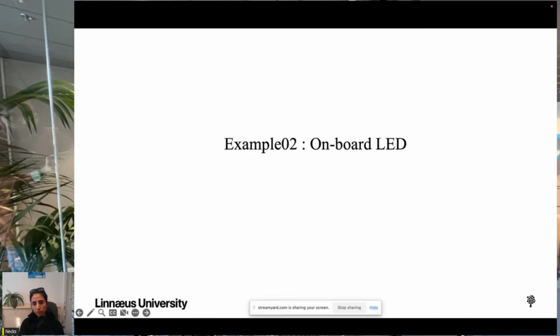So while you can't connect any external hardware to this pin other than the onboard LED, it can be treated just the same as any other GPIO pin within your programs, and it makes a great way to add an output to your programs without needing any extra components.